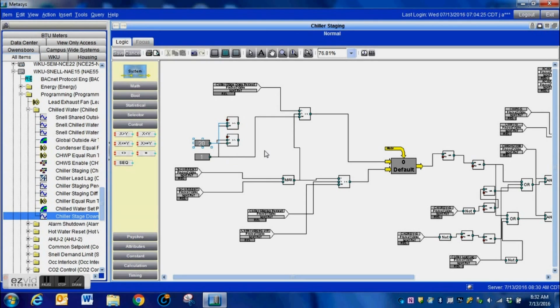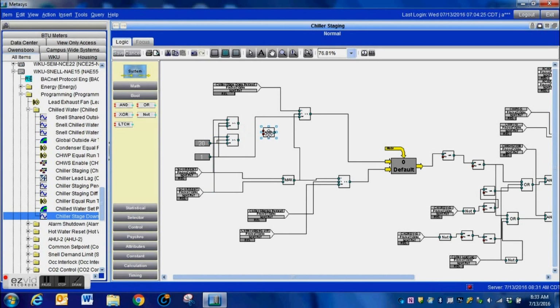And then I'm going to go and connect my output. Once again, this is my load from the chiller, each of the chillers individually. This is my demand. I'm going to connect those to those comparator blocks. Once the command or the load for both of those is greater than that 20%, what that is going to do is flip the AND block value. Once I make my connections here, the output of this AND is going to go to our selector switch.